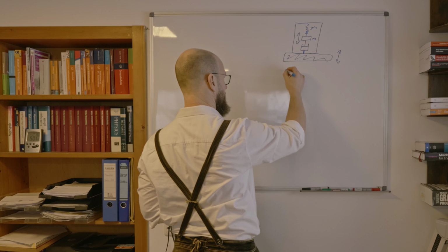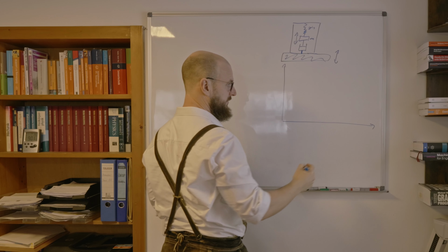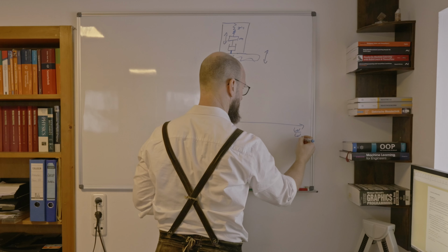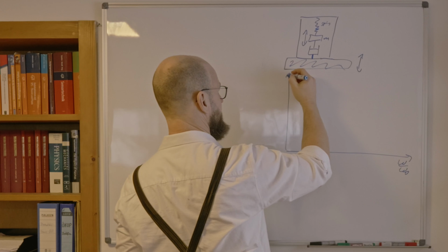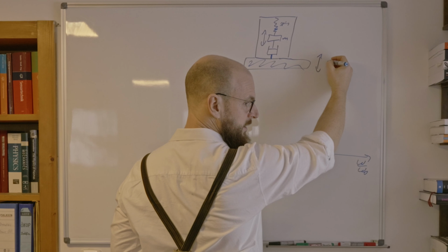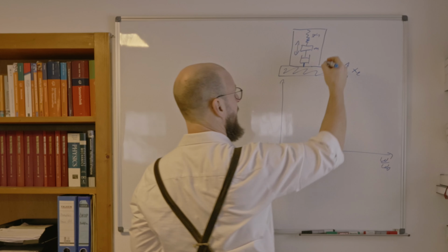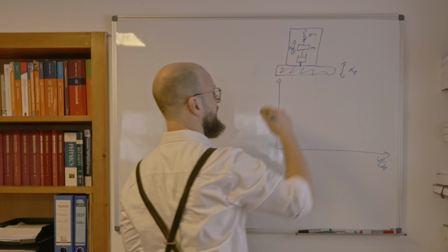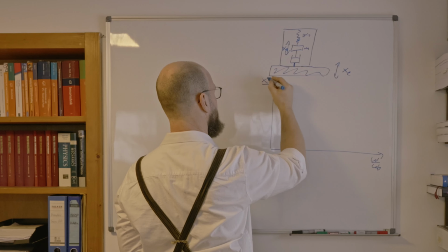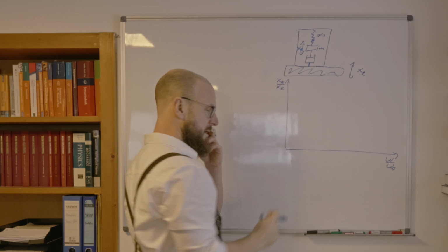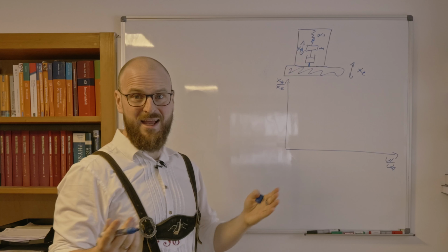But I will talk a little bit about the behavior of the systems in the frequency range. So we have some resonant frequency over here, and we have some amplitude xe of the movement of the external machine and xa movement of the inertial mass. So we can look at xa over xe to get the correlation of that movement to that movement, and that's interesting for us.